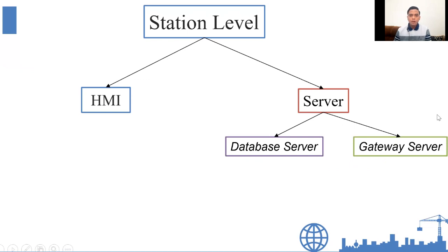And for the server, a hardened computer with the SCADA application installed communicates with IEDs to provide monitoring and control of the power system. The database server, or DB server, has the main SCADA application software installed. It communicates with the IEDs in the field to gather data and to send control commands. Data consists of real-time analog values, indication, alarm, control, and set point. Two computers represent their data on the SCADA HMI.